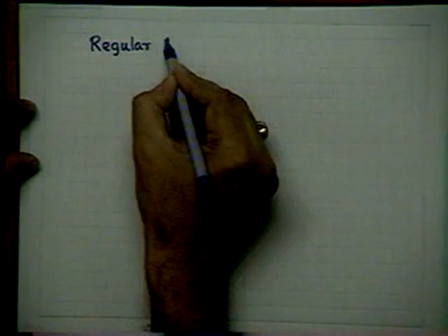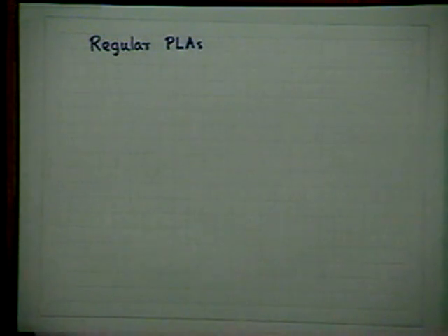And if I want to really think in this kind of way, the way I have drawn the block schematic, it ultimately appears to be rather complicated. But we shall see just now that from this basic block, I can create the PLA, which is very simple so far as VLSI implementation is concerned. Consider now the same thing realized by a regular PLA structure. We shall see that PLAs can be divided into regular PLAs and folded PLAs. We shall see that PLAs can be folded and compacted. But whatever I am now discussing are simple regular PLAs without any compaction.